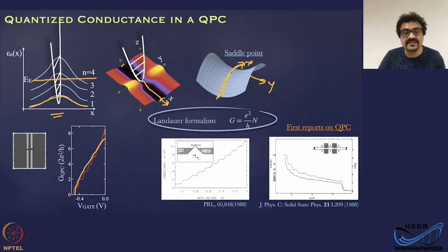But in this case, you also have a small gap. That gap is going to create a channel, and the electron energy is quantized in the channel. So when you sweep the gate voltage, you will basically change the number of levels available for transport in a step-like manner, and you will see that in the change in the conductance or current also.